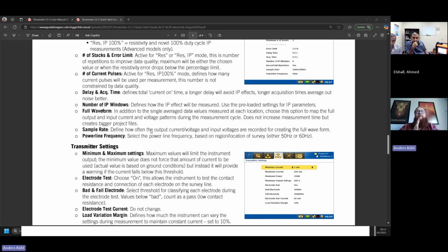That's why the sample rate says 1,000 or 1,200: 1,200 is for the 60 hertz and 1,000 is for the 50 hertz setting. It measures at a multiple of 60 hertz and thereby phases out the contribution.